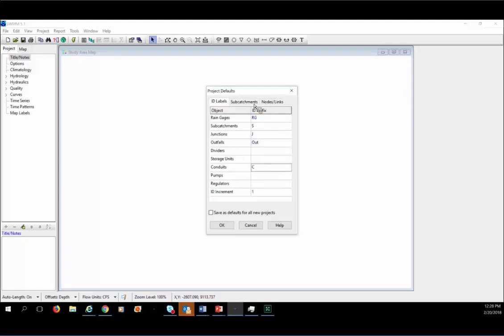And then I'm going to have default sub-catchment and default node lengths. You have an area, you have a width. The area is 5 times the width, percent slope, percent impermeable. Let's say I'm going to say 50% of my sub-catchments are impermeable. If I want to adjust this sub-catchment by sub-catchment later, I can. I have the Manning's N for impermeable, Manning's N for permeable, D-storage for impermeable and pervious, and percent zero for impermeable.